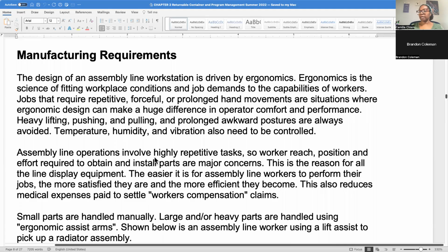You've heard me talk about things like lean manufacturing and how important it is for the material to be near the operator. I think I even mentioned what was called the strike zone, which is a term that's used to say this is the ideal space for the operator to work. It would be the same as striking a baseball. The umpire has deemed that this is a comfortable level for you to hit the ball, you should have been able to hit the ball. That's really the working space that is considered to be comfortable and ergonomic for an operator.